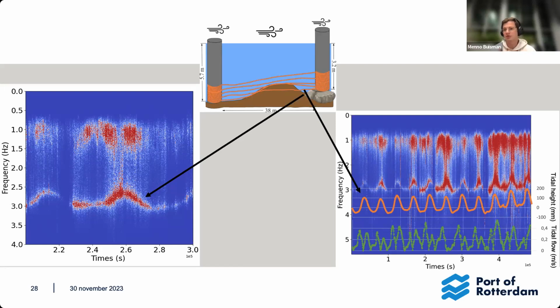Whereas with temperature sensing, you only know, okay, I have a certain temperature, but I cannot say, is the cable partially damaged? Is the corner a bit too sharp and hence it's heating? Or is there not enough sediment? So that's why I think these two methods complement each other quite well. And that we should use more DAS on windmill export cables.